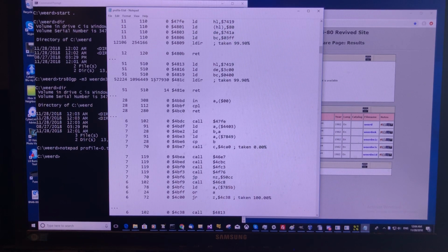And actually here we've got a huge number of wait states. This block move instruction was executed 50,000 times, which is, I guess, about 50 screenfuls. And in fact, we can tell just looking at the code here, it's copying to DE, which is 3C00, that's the address of the screen.